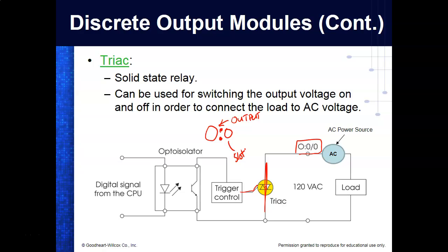On a rack PLC, slot 0 is occupied by the CPU. On a fixed PLC, the CPU does not have a slot. So your first I/O device would be at what we call slot 0, even though internal. And then we put a slash, and then we'll put a bit. So this is the bit address. So O means out, followed by the slot number, followed by a slash, followed by the bit address. So all our inputs are single bit inputs and single bit outputs.